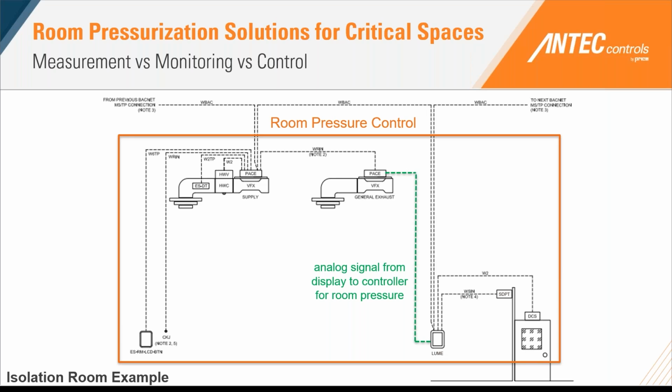So if that reading, let's say, is higher than our set point, our air valves can now react to that change, and vice versa. If your pressure reading is lower than your set point, the valves can now react in order to maintain the ideal state in that space.